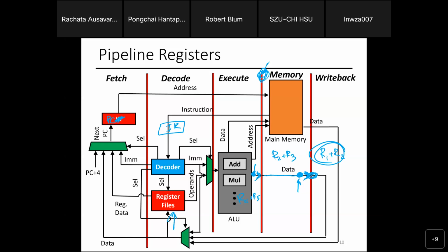The input will come from somewhere, and when you move the clock, the sequence of input will flow in. Your hardware will compute everything you design for that clock cycle until it hits the end, which is the buffering area for the next step. And when you clock, the buffering area takes the input, replaces the old one, and it keeps doing this. Not sure if that's a good explanation.